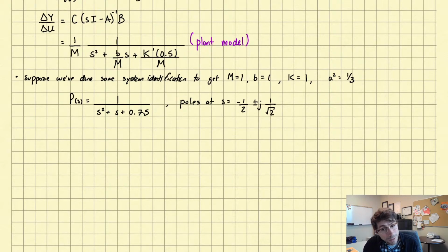Okay, so the plant is open loop stable, right? I don't need feedback to stabilize this plant. In other words, if I just apply this constant u bar, this force, this mass will eventually settle down at the desired location, 0.5. So it's not like the pendulum example last class where it was open loop unstable. This case is open loop stable. However, the spec was step tracking, so we still want to be able to accomplish that.